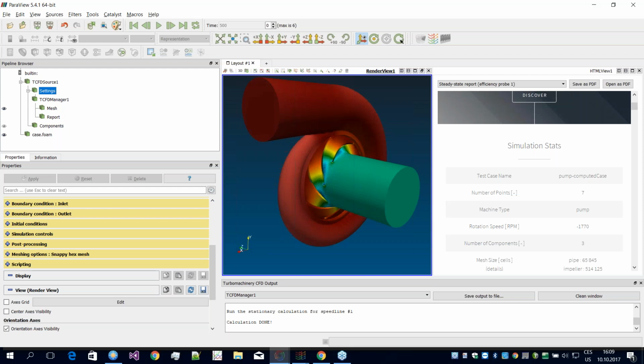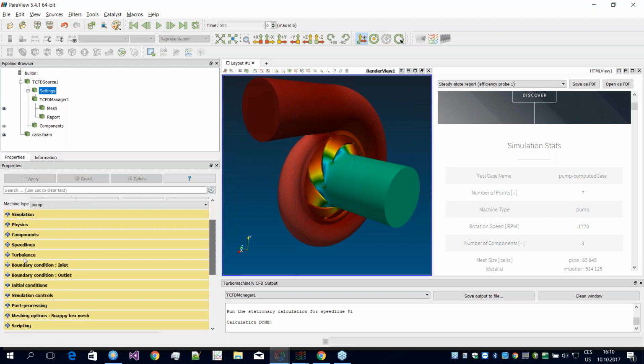Okay, so if you mean the fully structured or block structured hex mesh, we are not able to do that with the snappyHexMesh tool, which we are using. It creates the dominant hexahedral mesh, but let's say, it changes the shape of the hexas like tetrahedras in the neighborhood of the surfaces. But there is an option to add layers.